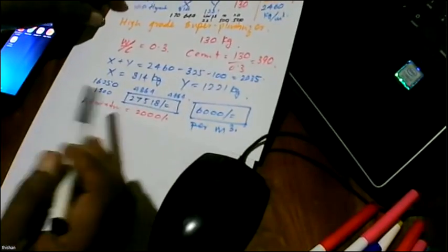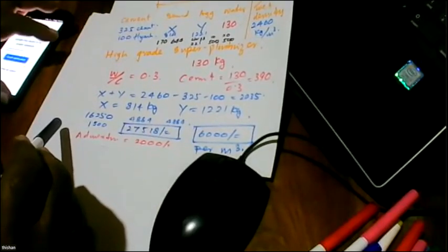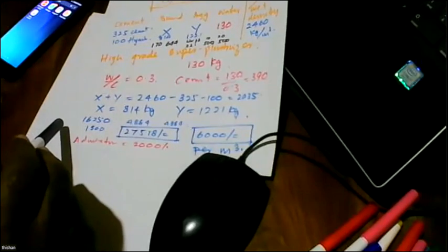Right. So now we have to see how we can achieve even higher strengths, because now we are using only 325 cement. I will tell the method, but I cannot give an exact answer when you are going for super high strengths unless we do the testing. But I can certainly indicate the trend. So let's say we go for C50-60 concrete. Now how are we going to deal with this?